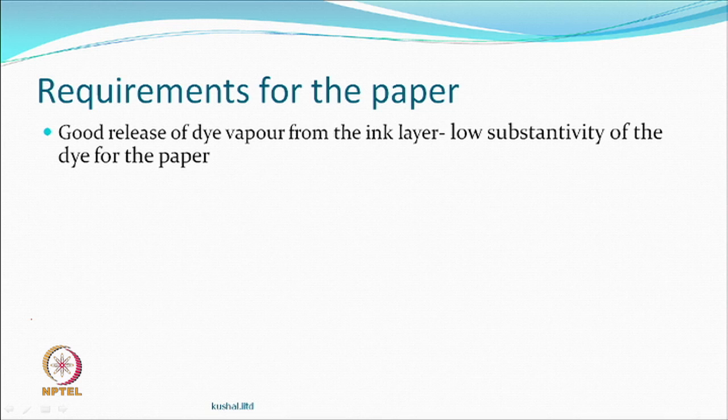Not only that, the viscosity of this ink when it is being printed is much lower compared to what we use in textiles, because the technology is generally different, which is acceptable, the commercial technology is different. It is expected that it should have low substantivity. Fortunately, cellulose and dispersed dye do have, but from the point of view of a principle, it could be any paper, any sublimable dye, any textile could be the one which accepts there.